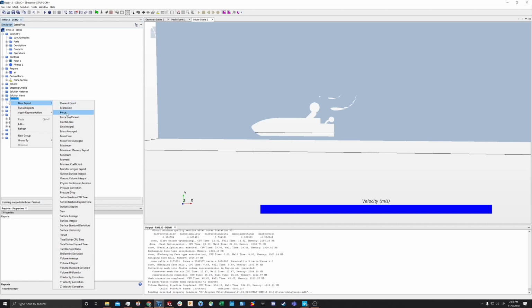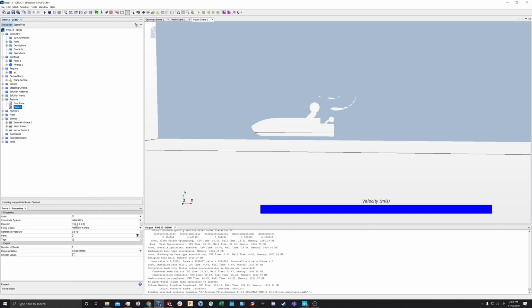And then we're going to make another one for drag. In the way that I've got this sim set up, drag will be in the positive x direction. I actually didn't need to change that. Nice. Drag is that force pulling opposite to the direction of motion of the car, so positive x direction in this case.